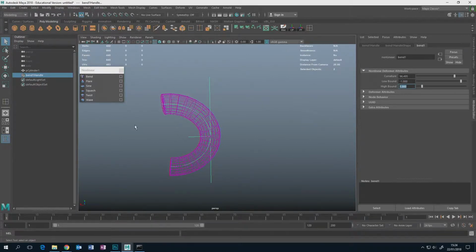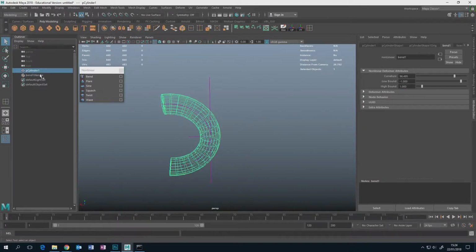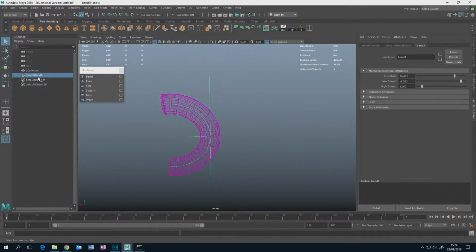Oh yeah, just another one. Say you want to create a primitive, but you don't want to go up here. If you hold down Shift with nothing selected and hit Shift plus the right mouse button, it gives you all your primitives. It's got a very useful one here called Create Polygon Tool. Expert level, this one. Create Polygon Tool lets you click the vertices and create a brand new polygon object.